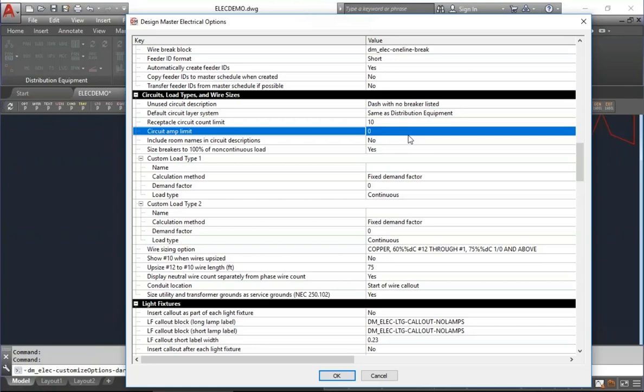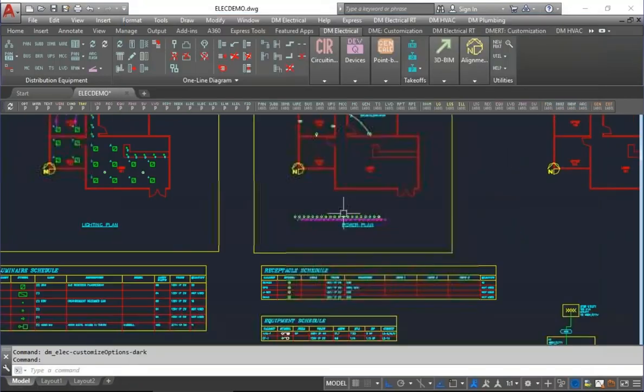And then when you're done, put it back to 0 so that when you're doing your motor loads and things that are obviously larger than 16 amps, it just kind of ignores you and goes along with that. So if I change this here, set that to 16 amps, click OK.